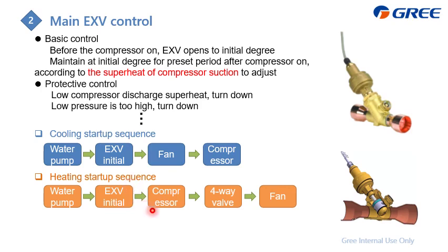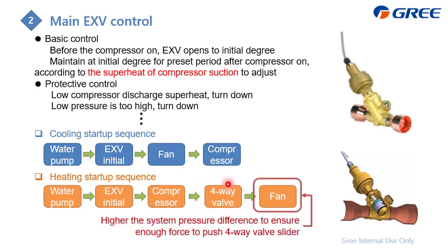Do you know why it is different between cooling and heating, especially for the fans? This one and this one. The reason is that we need to push this four-way valve, because it relies on the system pressure difference to push the four-way valve slider. So we must wait until the compressor turns on and operates for a little while. Then we can get enough pressure difference to ensure enough force to push the four-way valve slider.